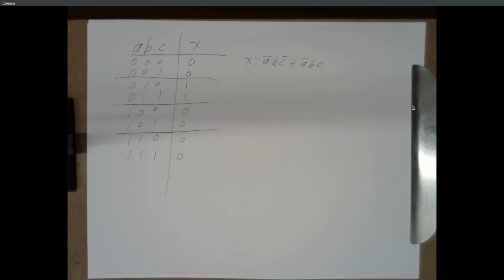Can you simplify? Okay, so that's a good compact form. Simplify that? Yeah, why? So these inputs, A bar B C and A bar B C bar, are the same. So pull out C or C bar, A bar B. Oh, yeah, because C doesn't matter.